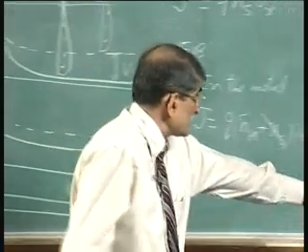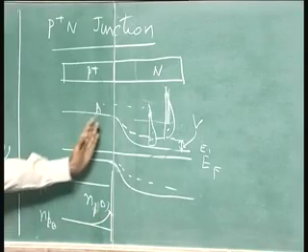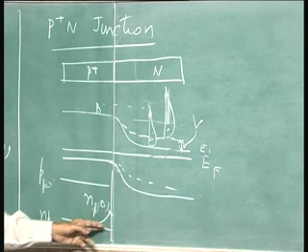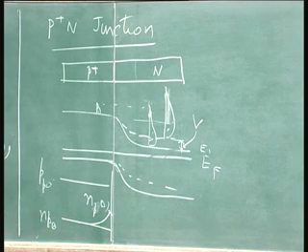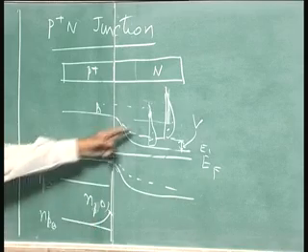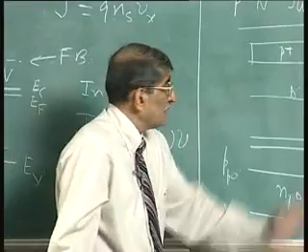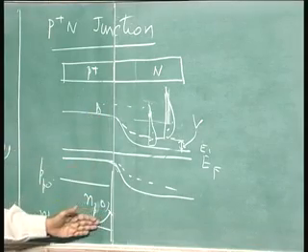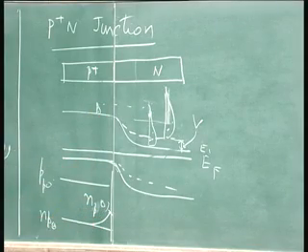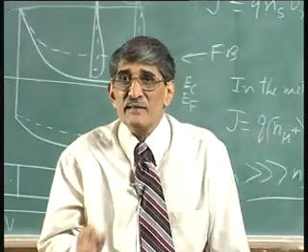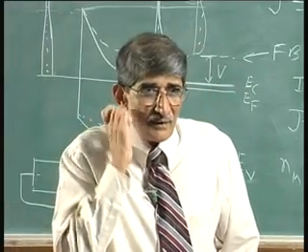Because of this concentration gradient, once the carriers cross the barrier, the transport is by diffusion, and diffusion is actually a slow process. So, this is slow compared to the transport from here to here. The equilibrium is hit, so that the rate at which it is removed controls the total current. So, the difference between the Schottky barrier and the metal-semiconductor contact for a given voltage